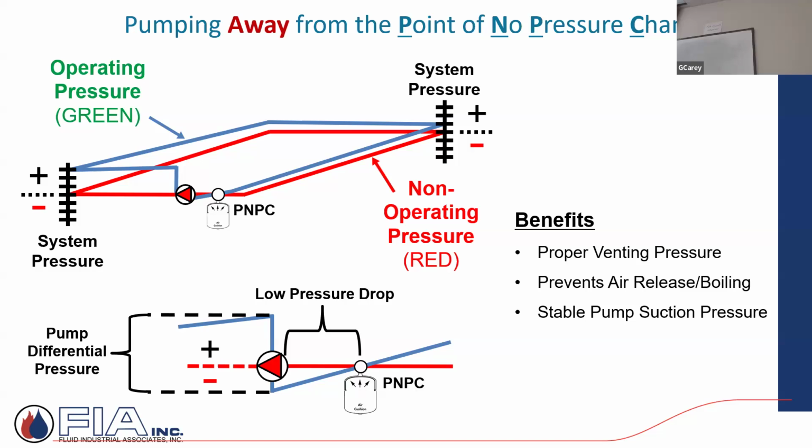When someone says, hey, put the pumps on the supply away from the expansion tank, well, why? This is it. I can change the volume of water. I can change the volume of air. Simply turning a pump on in a closed system, not heating it, not adding makeup water, just turning the pump on, I can't change the volume of water, which means I can't change the volume of air, which means I can't change the pressure. So the pump truly looks for that expansion tank.